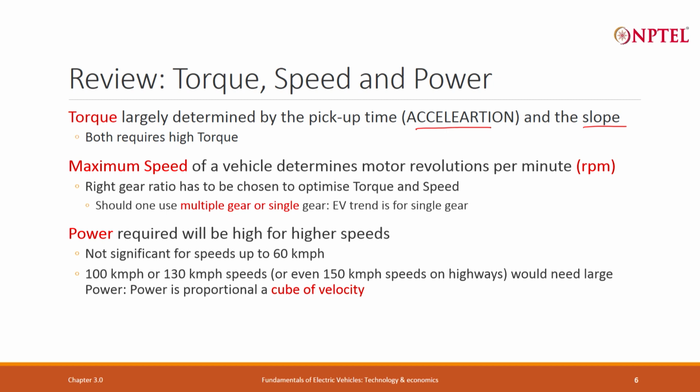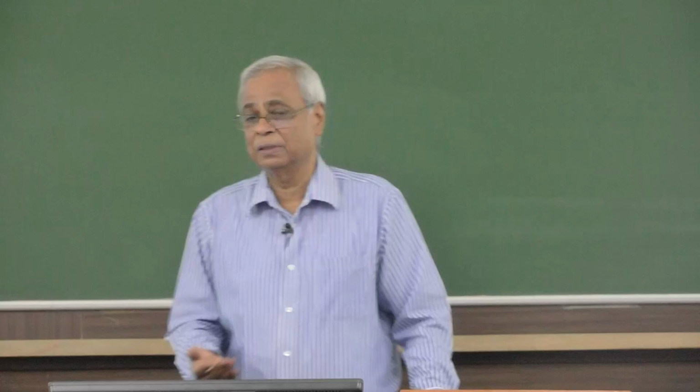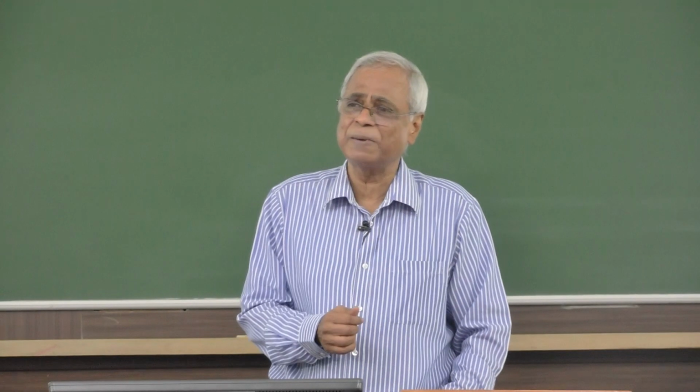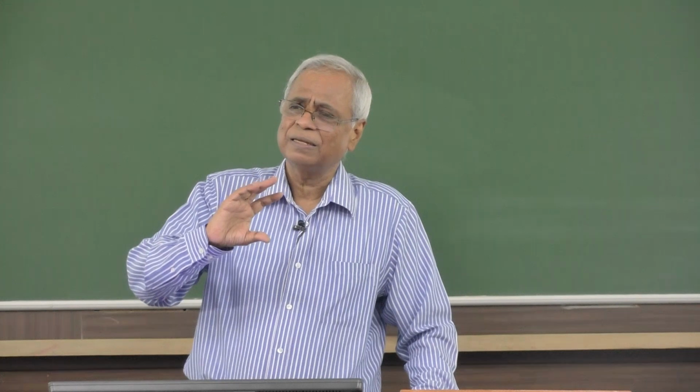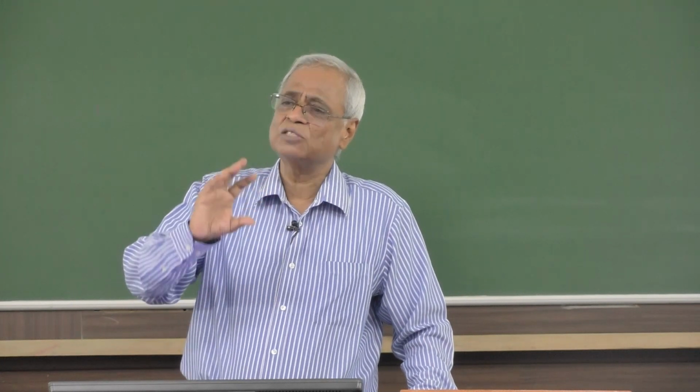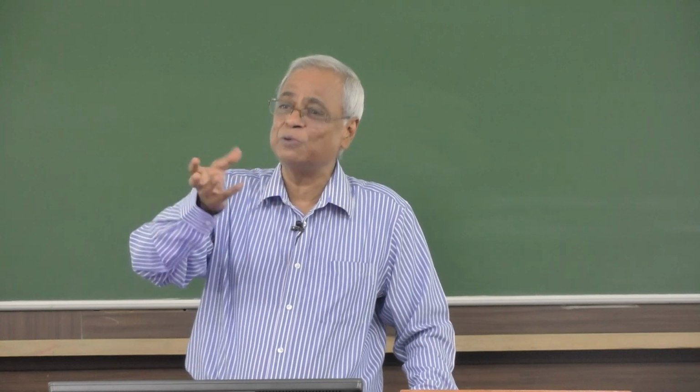Power requirement goes very high during high speeds. Somebody asked me, our belief was that on the last gear you use very little power. Not so, as the speed goes up, power goes up. The last gear basically means that the RPM is not being reduced significantly.